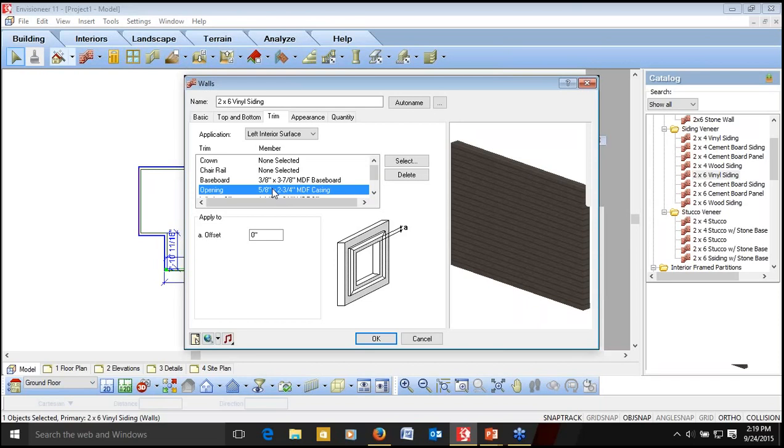Now, all of our trim lengths, again, can have that purchase member length. So I can tell it that I can order it in 10-foot lengths or 12-foot lengths, or I can leave it as just give me the total linear footage, and I can break that down into what kind of cuts I want to make out of that.